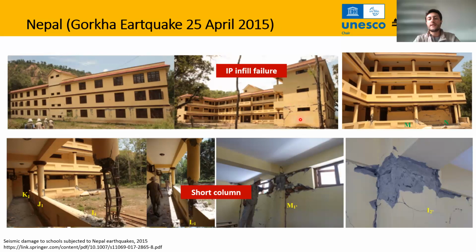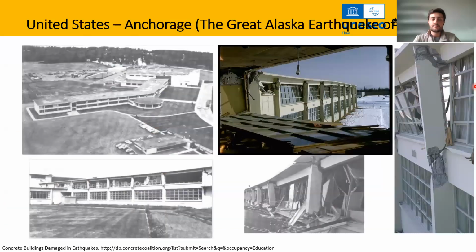So we can see that the infills are interacting with the structural frame, which is the second typology. Usually buildings are not designed to interact with this, but in reality, the interaction exists, and this must be considered when we think about retrofitting an existing building.